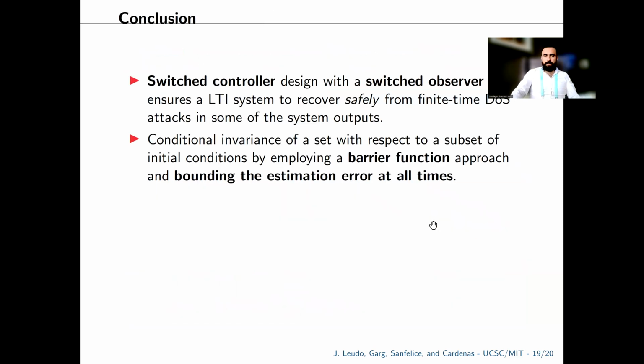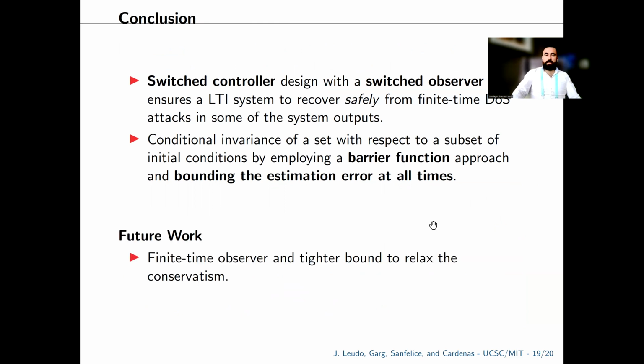Okay, as a conclusion, we presented a switched controller with a switched observer to recover safely from DoS attacks in the sensors, and we encode conditional invariants by employing a barrier function approach while bounding the estimation error at all times. Future work includes employing a finite time observer and a tighter bound that will relax a little bit the conservatism that we have in this work.